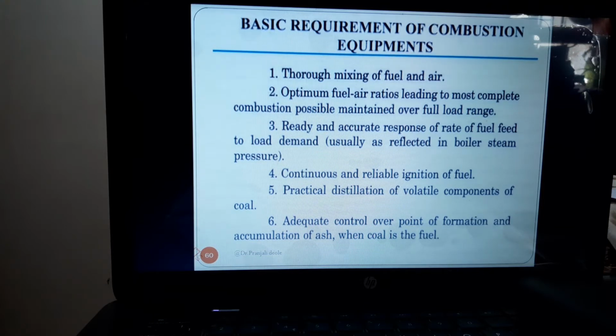Cleanliness and convenience in use are other criteria of selection, but more decisive in small plants than in central power stations. Transportation costs add less to the delivery price of the oil than gas. Also, fuel oil may be stored in tanks at a reasonable cost, whereas gas cannot. Hence, although fuel oil is usually more costly than coal per kg of steam generated, many operators select fuel oil burners rather than stokers because of the simplicity and cleanliness of storing and transporting the fuel from storage to burners.